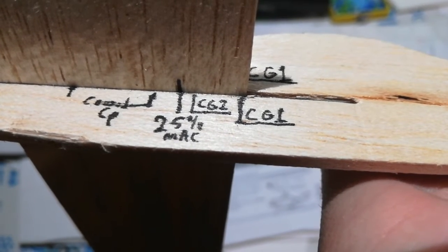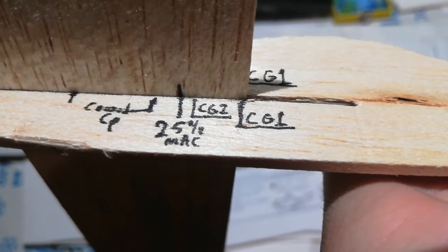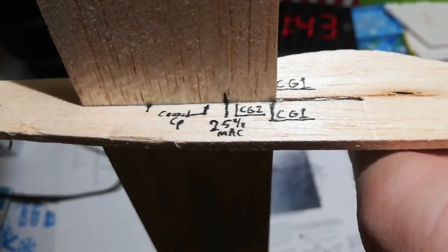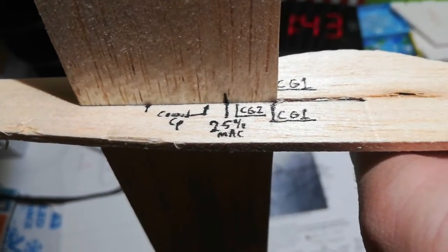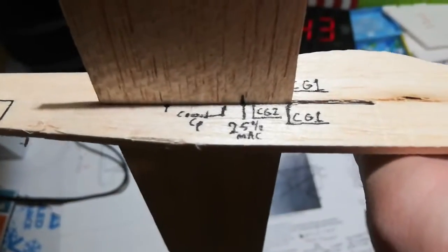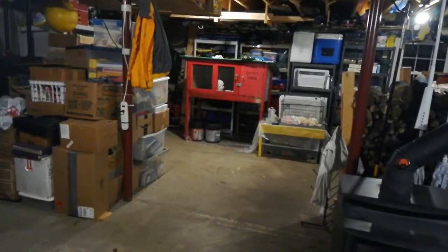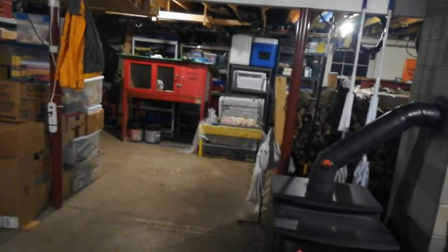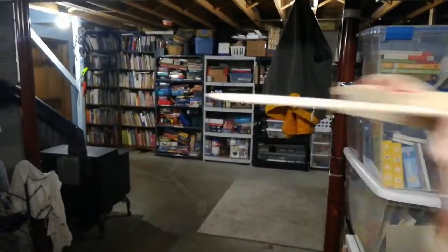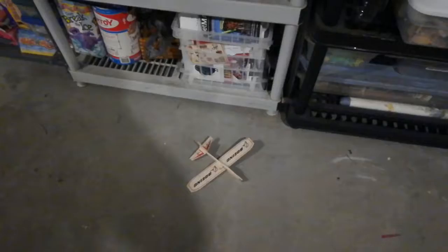Having the center of pressure behind the center of gravity will create a stable situation, as the tail has a negative angle of attack and will counter that pitching down motion caused by having this weight at the front with the center of gravity in front of the center of pressure. And with a test flight, we can see that now, with the wing in the rear position, it flies in a stable fashion and will just keep going straight until, that is, it hits something.